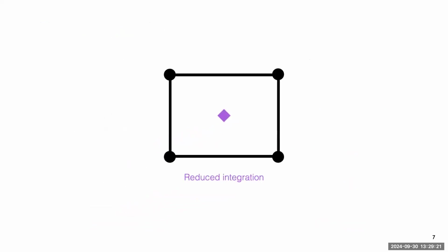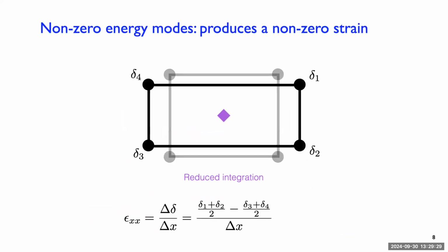So let's take the default element in Abaqus, and let's apply that loading case that I just told you about. So I apply this uniaxial loading. So it extends in the x direction and contracts in the y direction. Let's imagine that rigid body modes is not a problem here, that it's not drifting away. So it's forced to stay about the center. So it contracts in that direction and gets longer in that direction.